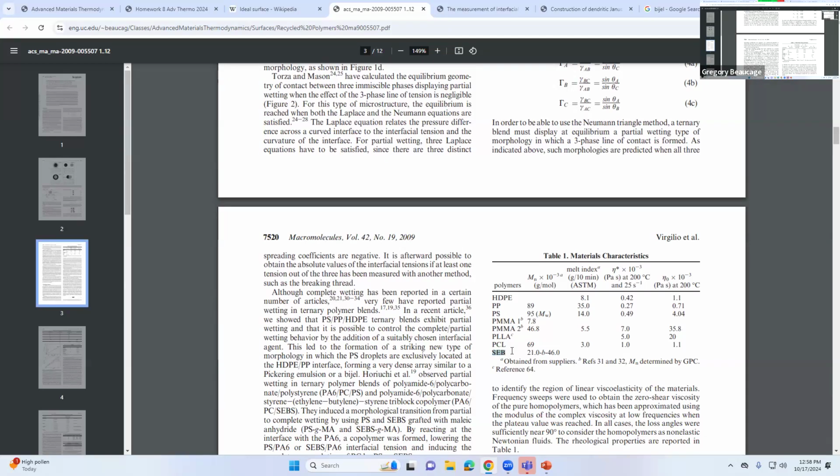So this is the copolymer, that's the miscibilizing agent. He gives them molecular weights, melt index, viscosity. Because he's going to use the viscosity in that equation, just when he does the fiber breaking method, he needs viscosity. So he spends a little bit of time talking about the viscosity measurement. And this is a plateau viscosity.